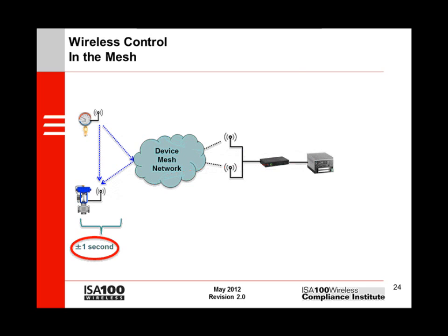You can also arrange to bounce the signal through a single mesh hop for redundant configuration, as shown. In a configuration like this, 1 second is a reasonable target as shown in the diagram, and the result is both efficient and effective. One advantage of this approach is that the connection and control algorithms continue working even if there is an interruption in service in remote components.